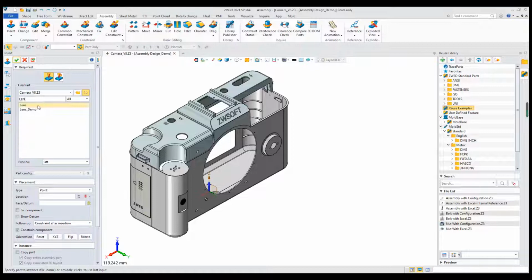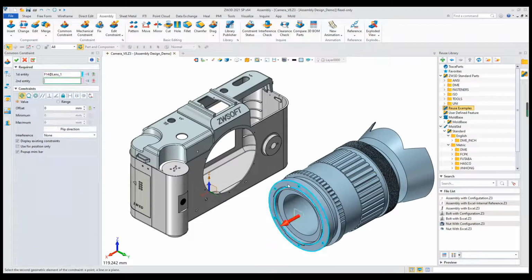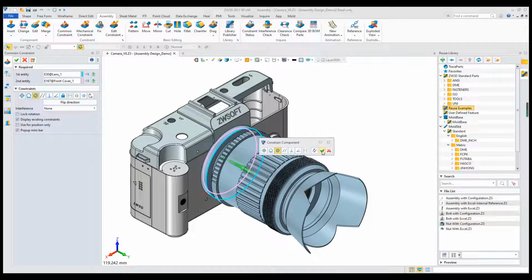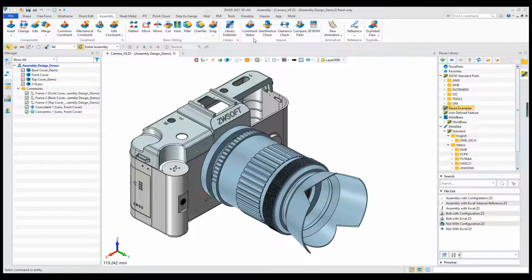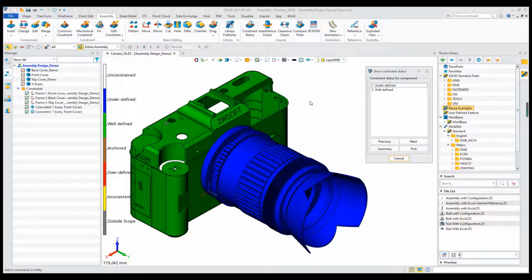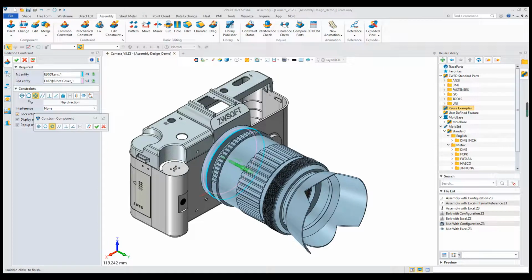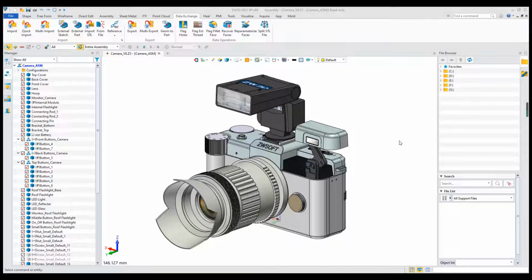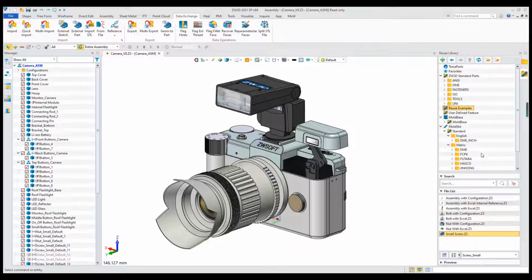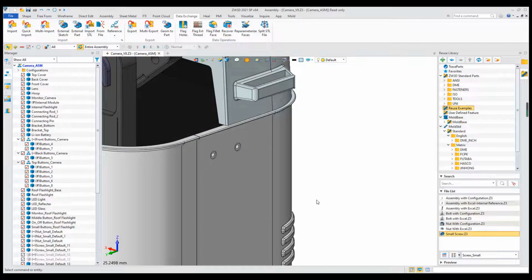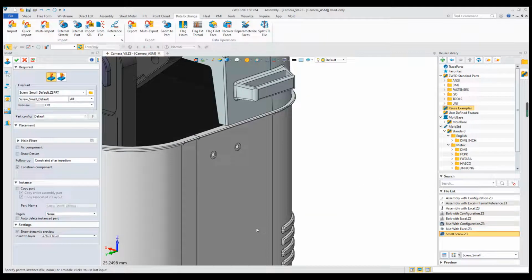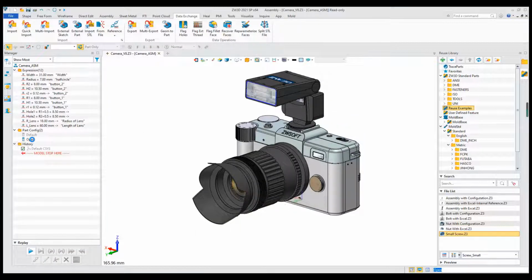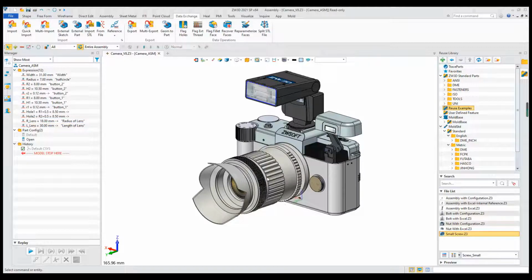The next step is finish the remaining assembly work by ZW3D assembly module. Let's mount the lens to the camera housing, add the constraints, and then check the constraint status. We find there's one underdefined constraint. We can redefine the constraint, and now the whole assembly is well defined. Besides, ZW3D has built-in standard part library and third-party libraries such as Part Solutions. Customers can also create their own standard part in the library. We can also create different configurations for the product models as well as the conditional suppress.